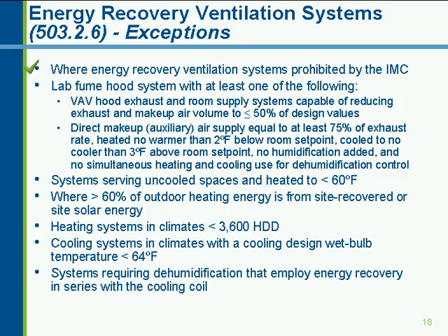you've got some alternatives. Instead of the energy recovery ventilation, you can install a VAV fume hood exhaust system that reduces the flow from that system to less than 50% of the design value. That gives you an exemption. If you've got direct makeup air to the exhaust hood system that's at least 75% of the exhaust rate and minimally conditioned, the requirements for that are heated no warmer than 2 degrees below room set point and cooled to no cooler than 3 degrees above room set point. You also cannot humidify that air, and you can't do any simultaneous heating and cooling for dehumidification control. So if you meet those requirements for a lab fume hood system, you don't need to do energy recovery ventilation.